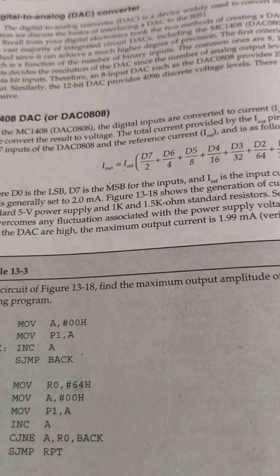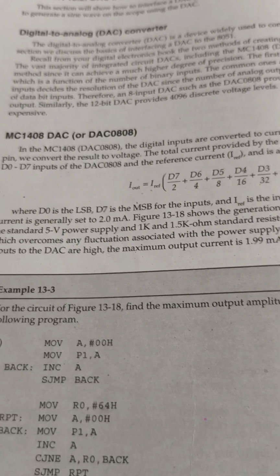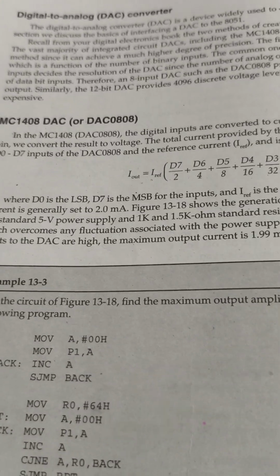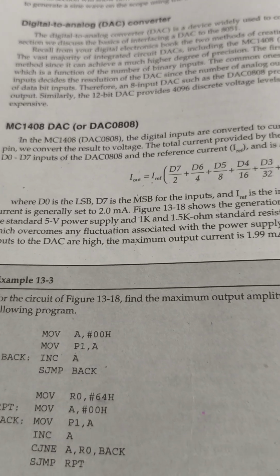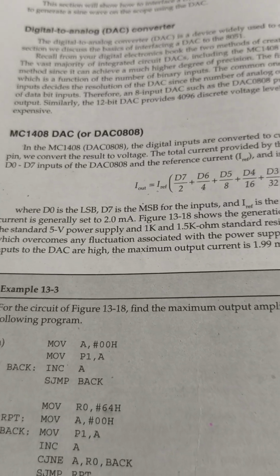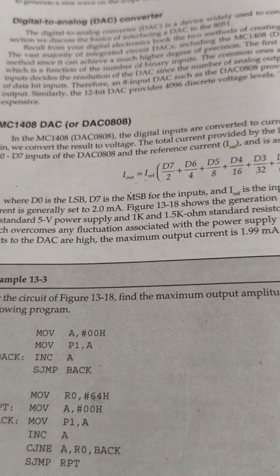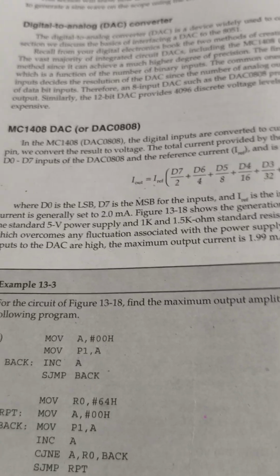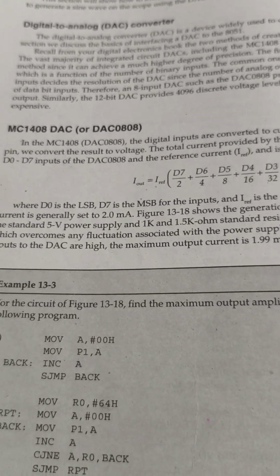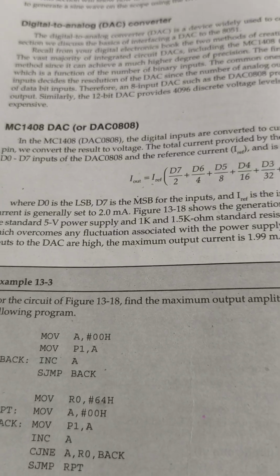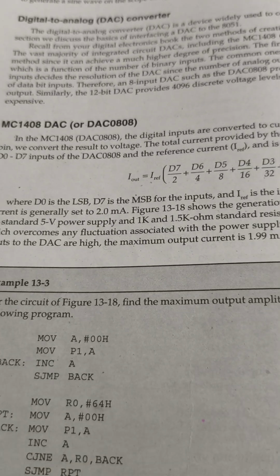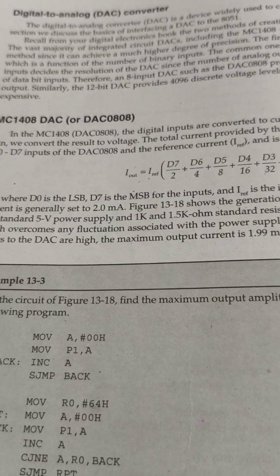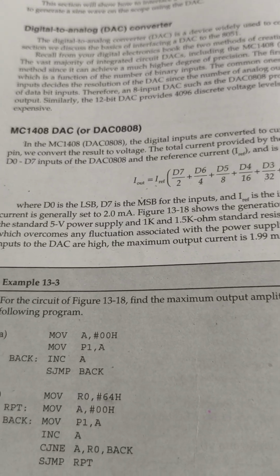If the speed of the induction motor exceeds 1000 rpm, it automatically stops the induction motor. If current exceeds 5 ampere, it automatically stops the induction motor. If voltage exceeds 230 volt, it automatically stops the induction motor. How? Because in the program we have written like that: if the speed of the motor exceeds 1000 rpm, stop the induction motor; if voltage exceeds 230 volt, stop the induction motor; if current exceeds, for example, 5 amperes, stop it.